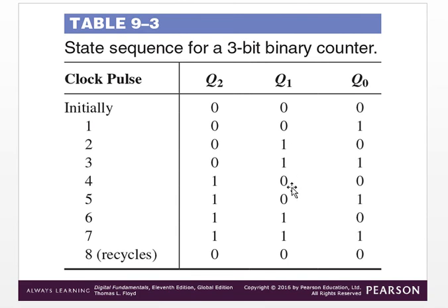Then no change. Then change. Then no change. Okay, so every 2, so Q0 and here Q1, Q0 and here Q1. See what is the difference between Q0 and Q1? In Q0, the inputs J and K are connected to 1, so every time it changes its state. For Q1 it is not like that, because there is a 0 1 0 1.